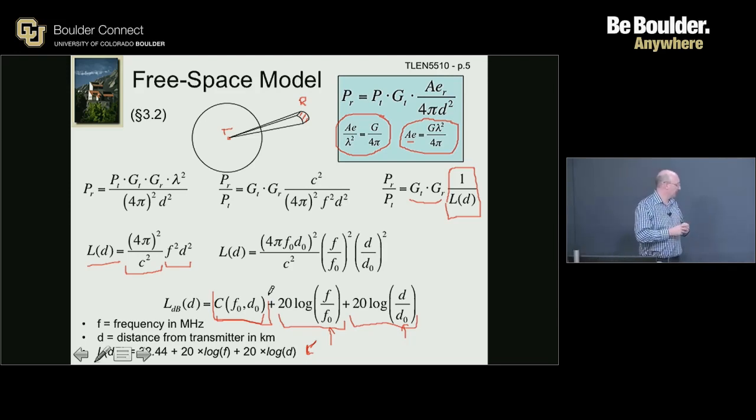Sometimes you change things and you use the path loss. Remember the units associated with the things inside a logarithm. So simple, obvious math, but sometimes if you forget it, there can be mistakes in link budgets. You can have a factor 1,000 that appears here or there, or 30 dB that start appearing here or there, and that can be embarrassing. Any question on that? Probably spent too much time on that slide.